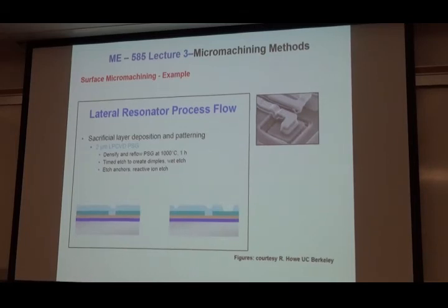Remember, the whole thing is 2 micron. So dimples are typically about 0.6 micron. By that time, already the photoresist is weak. Remember, everything will etch. It's just the etching rate that is better. Some of them would etch 5 microns per 10 minutes. Some of them 10 microns. So anyway, once I strip that one out, then you do the additional etch.